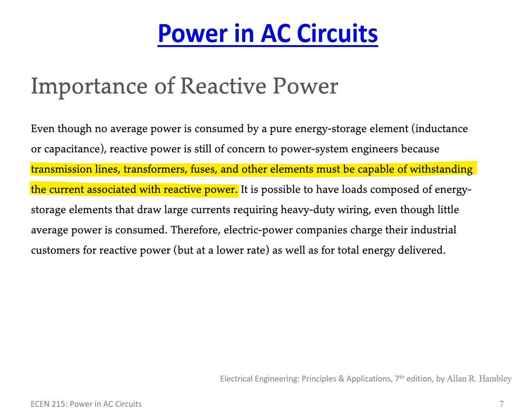And this is true even for the systems that you are going to be involved in your particular discipline. You have to make sure that the power connections to whatever device you're working on can handle the actual currents flowing through, in the sense of the size of the wire, and for insulation, you have to pay attention to what the voltages are. So this is very important, even though maybe the net power is low, you still could be having large peaks.